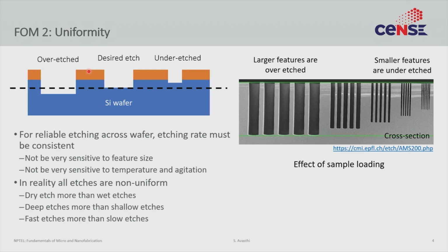So you want to have some sort of an agitation. However, if the agitation by its definition is non-uniform and that affects your etching rate, then that is also not good. So you have various optimizations that you want to do, where your etching solution should not be very aggressive or should not be too passive, right?